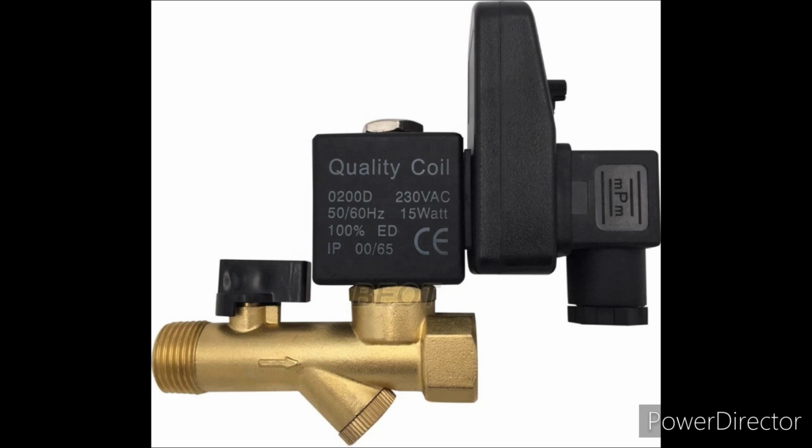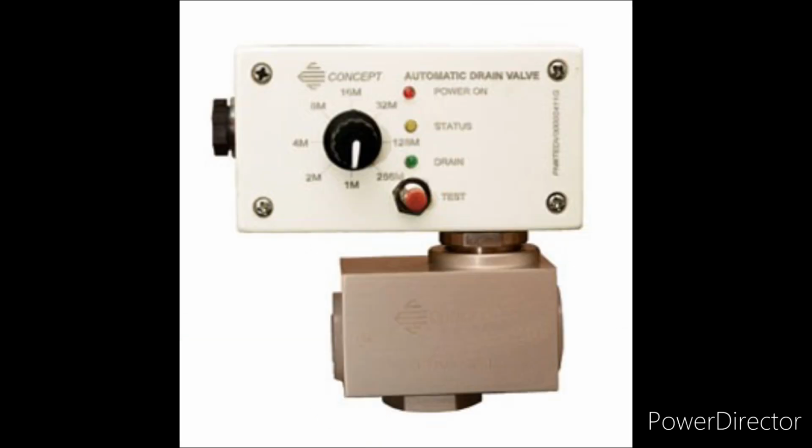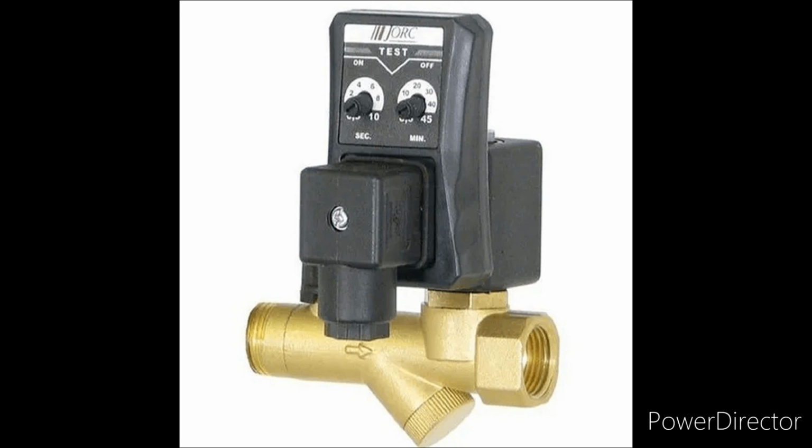Setting time 5 second per 5 minute. Okay, 5 second for 5 minute. Condensate discharged for 1 second and air lost for 4 seconds. So 12 times per hour into 4 seconds equals 48 seconds per hour. So operation of 24 hours per day for 365 days: 24 hours per day into 48 seconds per hour into 365 days per year equals